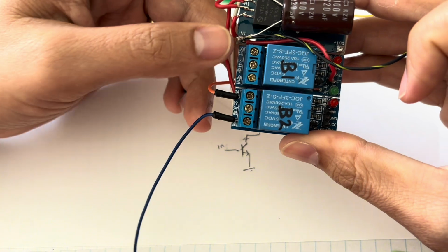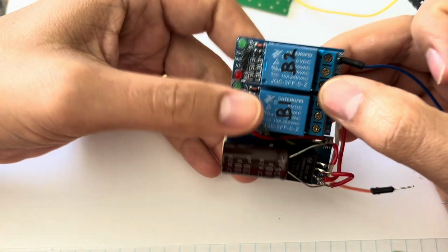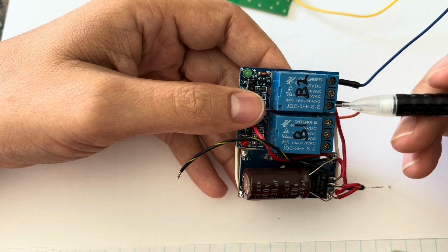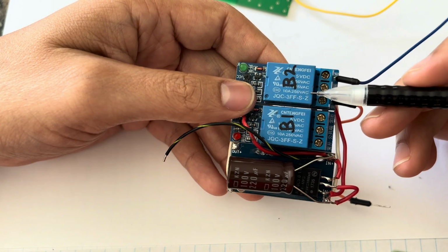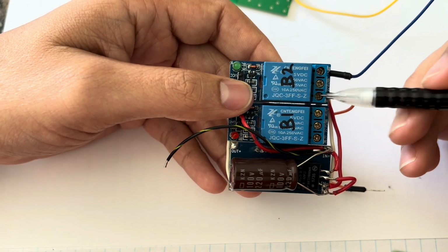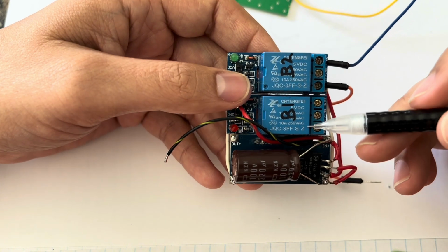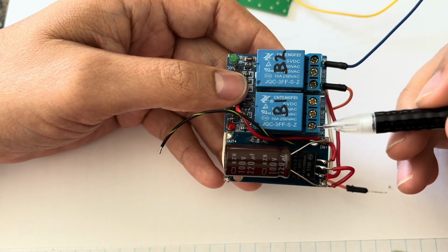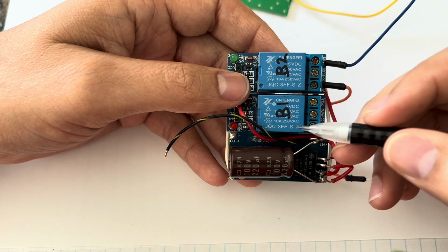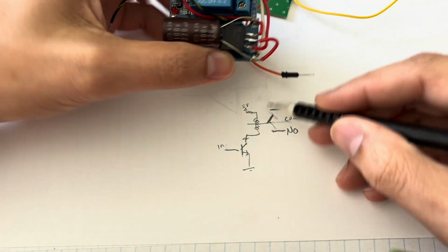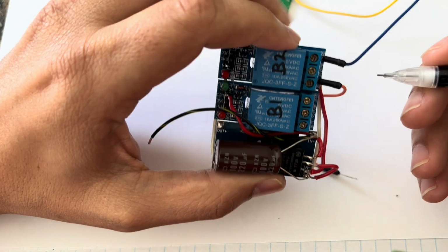Now, when using these, it's very important to know what kind of power you're going to be drawing. So obviously, you can use these over here. You can put 200 up to 250 volts, but your current is limited to 10 amps, right? So if you put more than 10 amps, you will fry this output side and it'll just break the circuit.